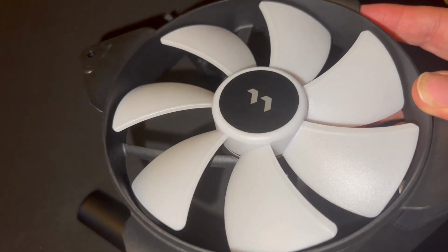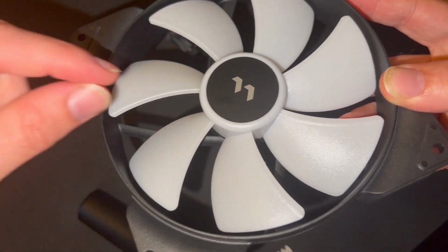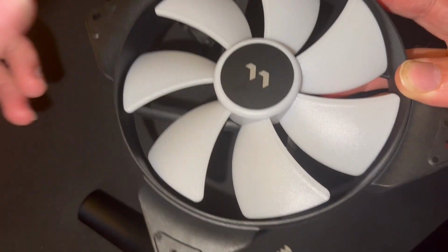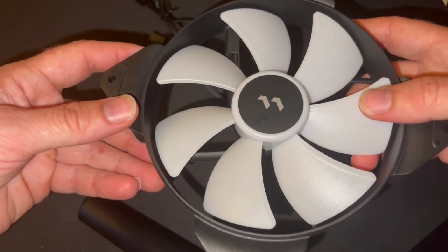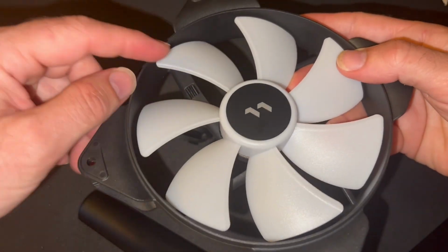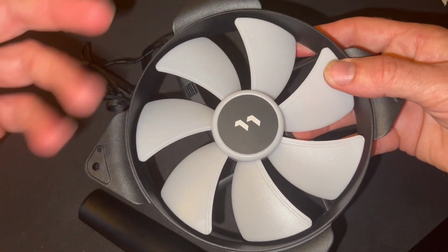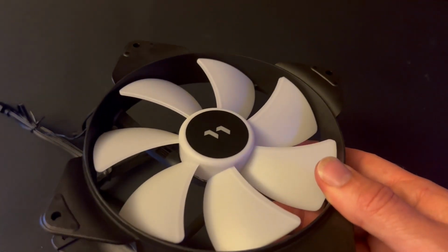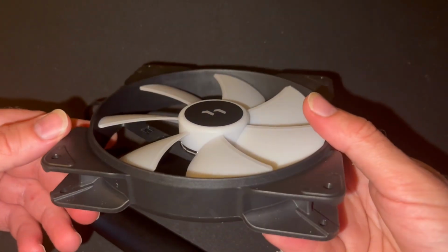And its purpose is to basically change the airflow to direct it back over the fan. So tripping it to turbulent or something like that, so that the air will travel along the fan blade rather than doing, well, something else. This is the only fan that I've, other than the other Aspect one, that has a feature more like this. Most other fans will have grooves or something like that along the fan blades, but not this little, I'm going to call it trip wire. So they are calling that a micro turbulent, which is supposed to improve the blade efficiency.